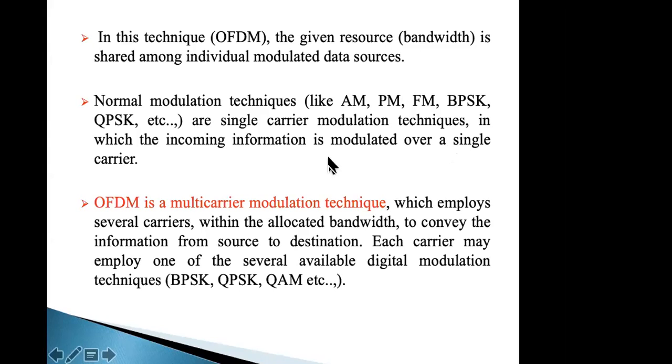I cannot go with frequency selective channels because they create a lot of interference. To avoid this, we still want to go with narrow bands, but multiple of them, since I have a huge bandwidth. This huge bandwidth is divided into smaller bands, and in each band I will send my information in parallel. That is what I am interested in. That comes under OFDM, orthogonal frequency division multiplexing.